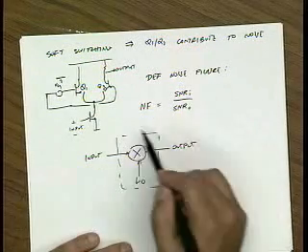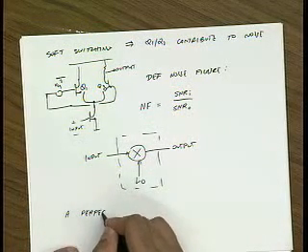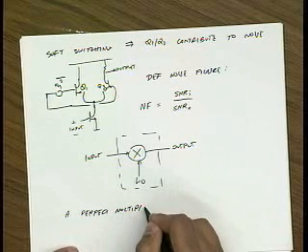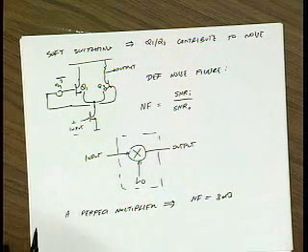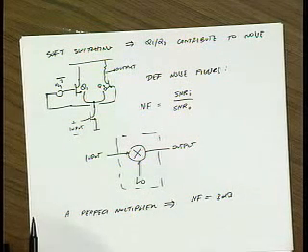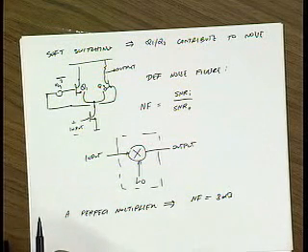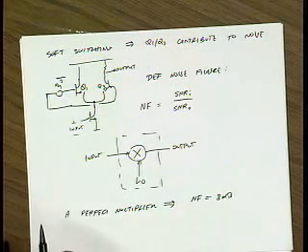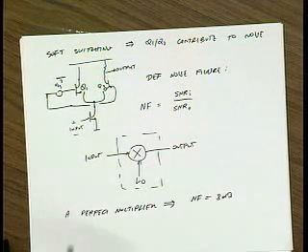Now, the reason this noise figure definition is complicated is that a perfect multiplier, as you guys all know because you did the homework, has a noise figure of 3 dB because of the image noise folding back onto the same band. On the other hand, someone looked at this and said that's not fair, that means a perfect mixer already has a disadvantage of 3 dB. What if we assume that there's a filter and that the filter actually rejects the image and the image noise? Then you would say the noise figure of an ideal mixer is 0 dB.